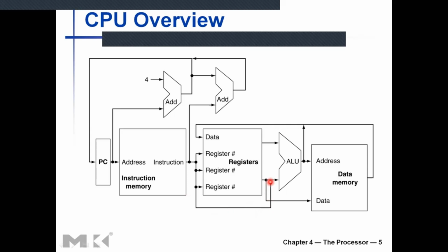Right? So a different path. Then the ALU can compute and give you a result. The result may be an arithmetic or logic result, or it may be a calculated address. If the result is an arithmetic or logic result or a shifted result, it can follow this path and go into the register file to be written into one of the registers given by these register addresses.